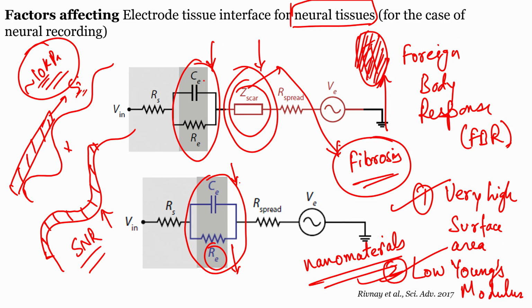What are the takeaways? Takeaways are as follows. 1. In order to model any kind of tissue electrode interface, you need to know what kind of resistors and capacitors are there. We took a case example of breast tissue, wherein there were two double layers, which are capacitors on either side offered by the tissue electrode interface, and the tissue impedance itself and the medium. Now remember, the medium may or may not be there, you may or may not have PBS, so you do not have to follow it point to point. In fact, this is just a direction in which you can think about.